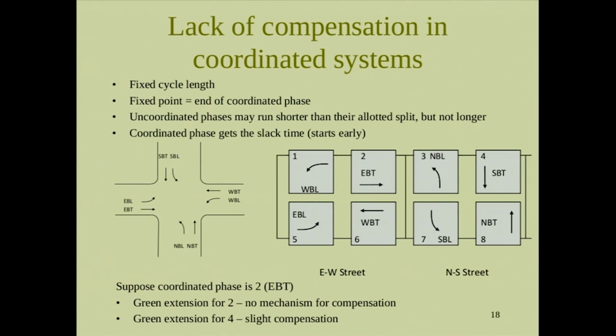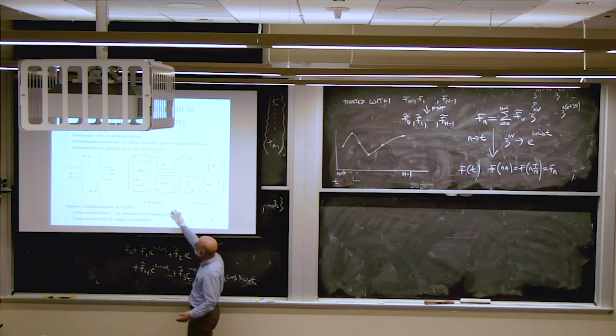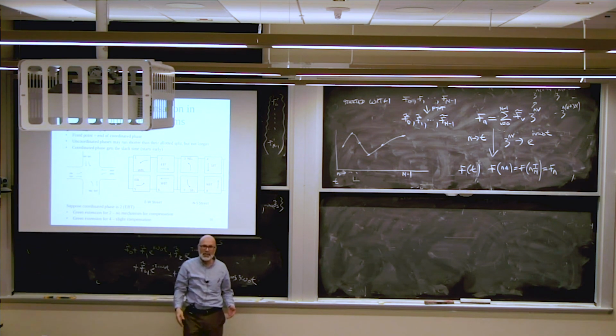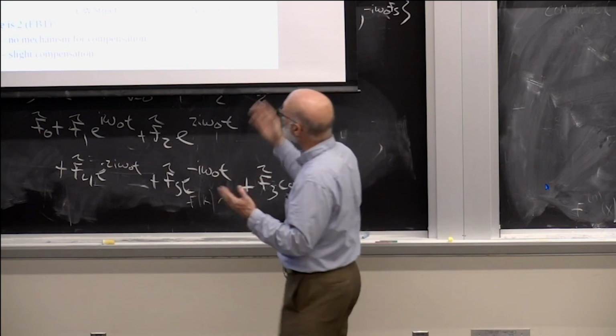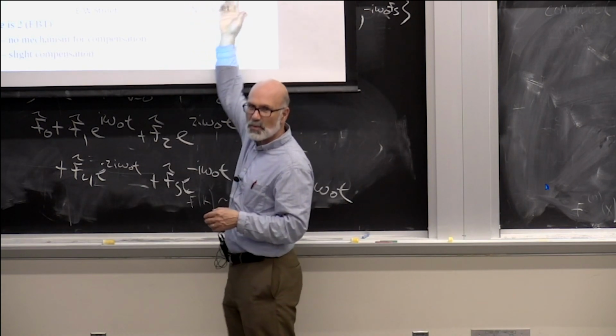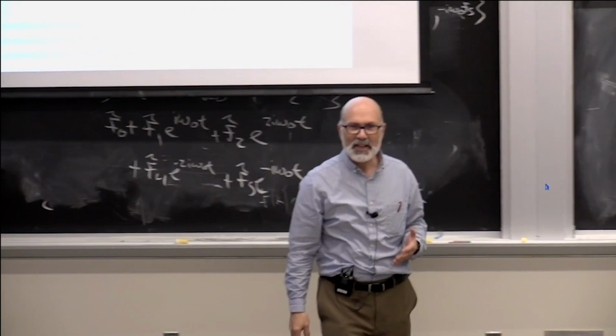So I have to take 15 seconds. The first generation, they would take the whole 15 seconds out of phase 7, and then phase 7 would just get canceled. Well, that caused big problems. So now what they'll do is they'll proportionally take it out. So let's say phase 7 is normally scheduled to have 20 seconds, and this one's normally scheduled to have 30 seconds, and this one's normally scheduled to have 20 seconds, so 20, 30, 20. That sums up to, what, 70? So I'm taking 15 seconds out, so a portion of that I'd take from you, I'd take from you, I'd take from you. You get the idea.